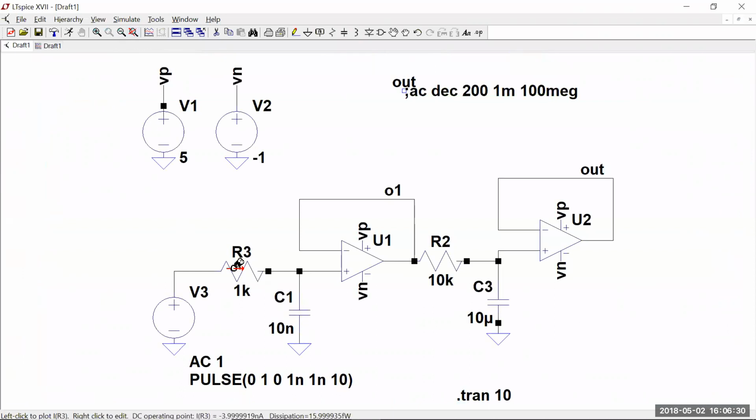And yeah, these op amps aren't really ringing, right? Because they're not really getting a step response. This is getting an exponential decay, and then this one's getting an exponential. So this is filtering the step function. So is this. In fact, so is this. So before it gets here, it's filtered 3 times, and then it's filtering itself the 4th time.